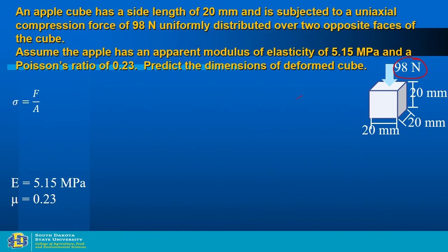Stress is force over area. Force is 98 Newton and the area is 20 millimeter by 20 millimeter. That gives you 0.245 megapascal.